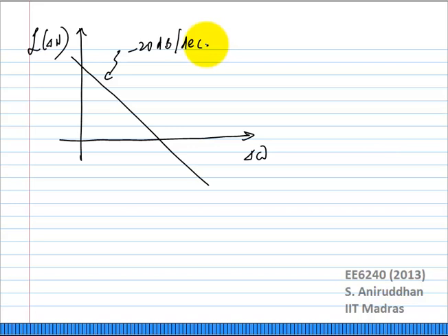So, the 1 over f squared region seems straightforward. What about the 1 over f cubed region? How do you think you would explain that? Correct. If you inject flicker noise where you are injecting thermal noise, you would get the 1 over delta f cubed. The 1 over delta f squared will come from the frequency response of the tank. The other 1 over delta f should come from the behavior of the noise itself to give you a 1 over delta f cubed region.